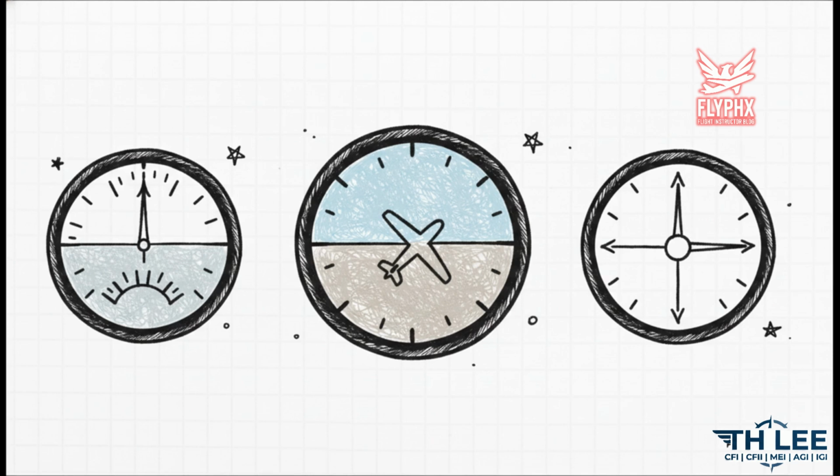Note that carefully. The attitude indicator does not indicate altitude or speed, it only shows your immediate pitch and bank. You must cross-reference your performance instruments to see the results of those control changes. Finally, navigation instruments, which include things like your glide slope and course indicators, tell you your exact position relative to a ground facility or a GPS fix.